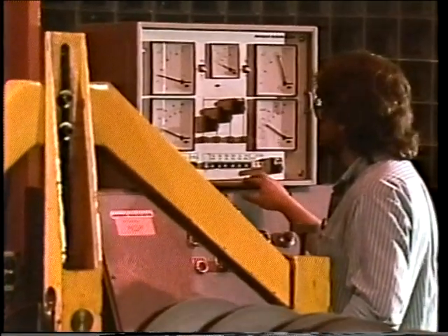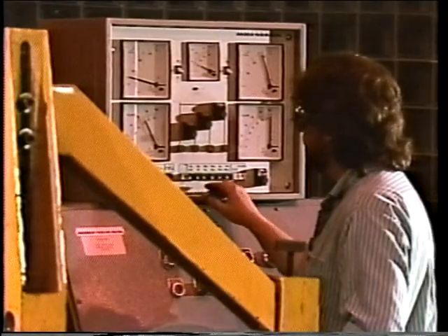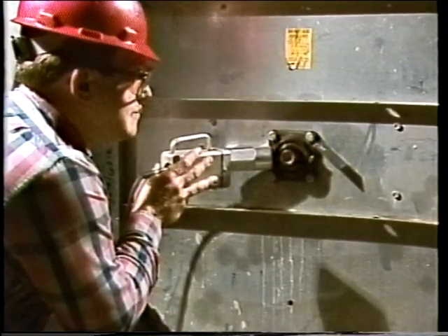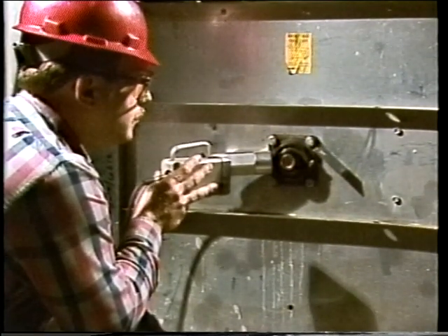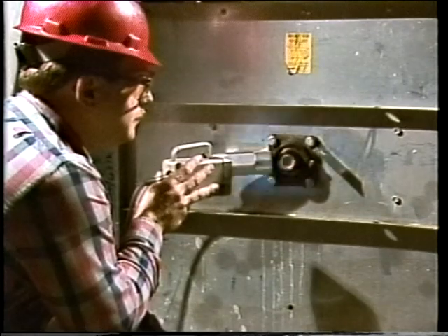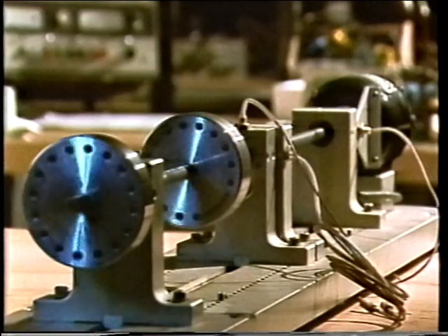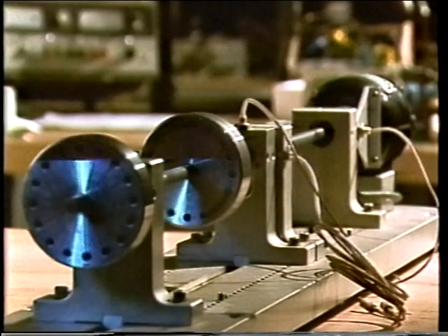One way to check the vibration that results from an out-of-balance shaft is by measuring its phase. Phase can be measured using a strobe light that's connected to vibration analyzing equipment. The vibration equipment will cause the strobe light to fire once during each revolution. When the strobe light flashes, keyways, couplings, and marks on the shaft will appear to be stationary.